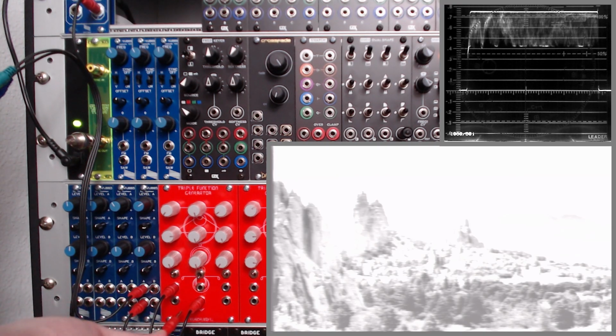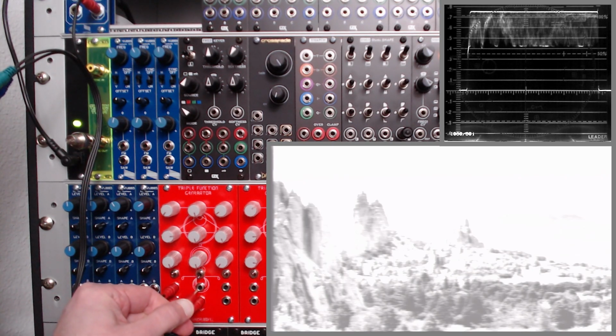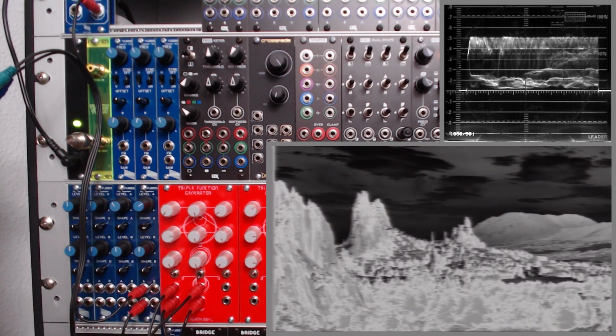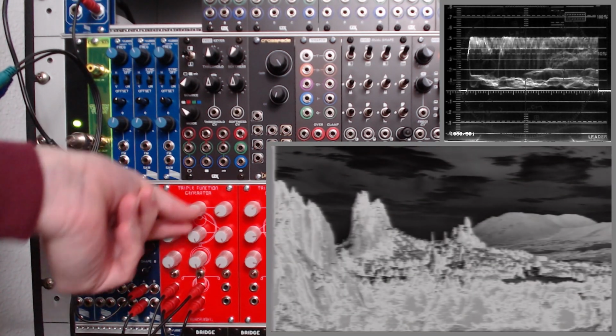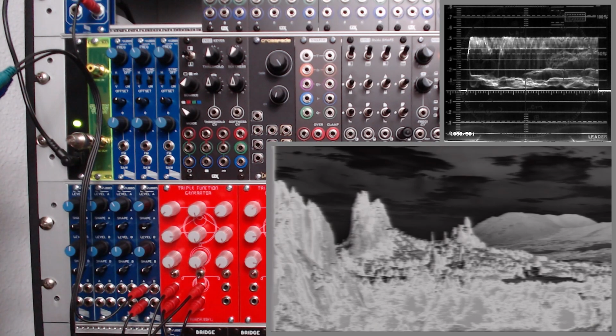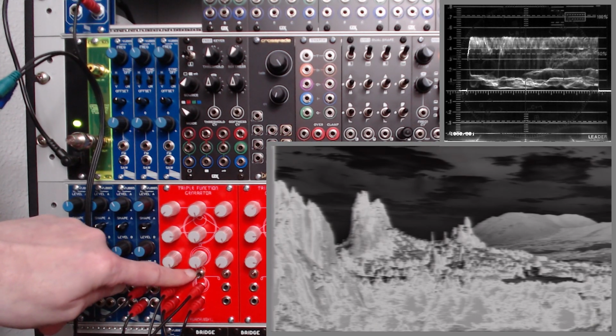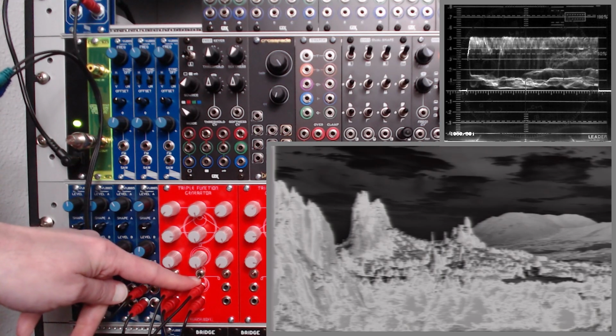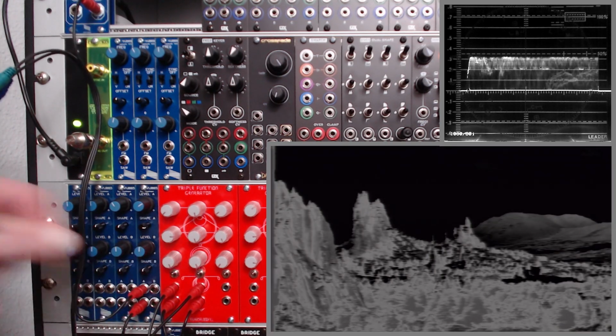I want to actually daisy chain these channels. Okay, so I'm going to do these in series, taking the output of channel 1 of the function generator, plugging it into the input of channel 2 of the function generator, and that gives me the ability to actually just amplify the signal. And the way to do that actually is with this switch in the up position. It's actually going to bias the incoming signal so that the circuitry works with the LZX 0 to 1 voltage standard.